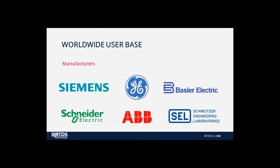And these companies have really integrated hardware-in-the-loop testing into the development and acceptance testing process for their protection equipment, including generator protection. Basler Electric, for example, has done HIL testing of their commercial AVRs, and Schweitzer Engineering Laboratories recently completed extensive validation testing of the SEL 400G relay, which has transverse differential protection and turn-to-turn fault detection. So it's their recently released advanced generator protection system, and that was done with the RTDS simulator.